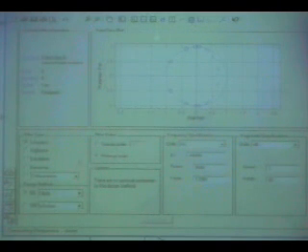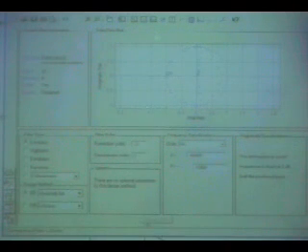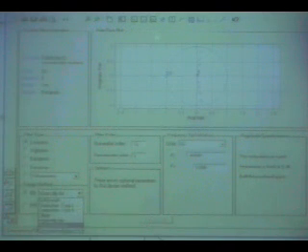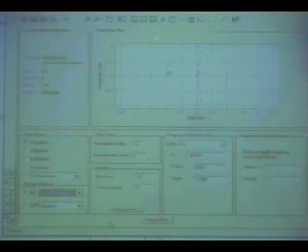Okay, you can try some other options MATLAB has provided, let's say maximally flat, I don't know what it will do. So let's see, it's 10th. Okay, it's a 10th order. If you are saying maximally flat, it'll try to make the frequency response smooth, but it is still more than 8. Then you say least pth norm. It says 8.